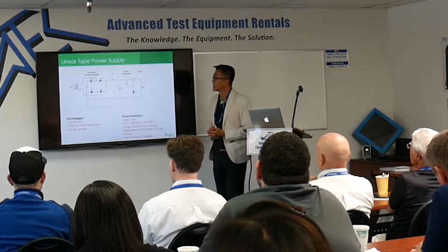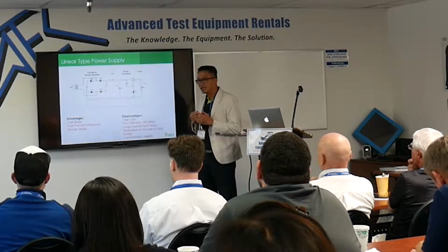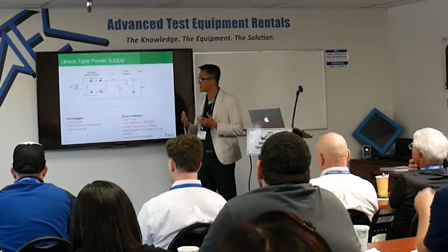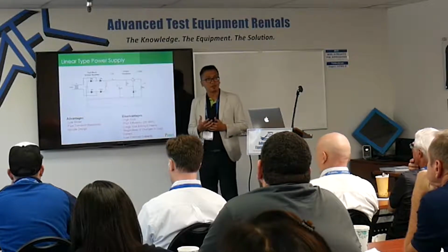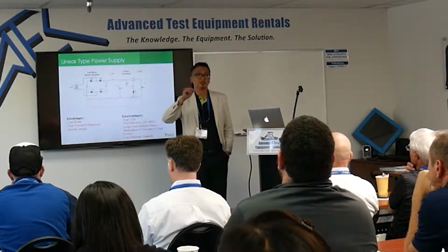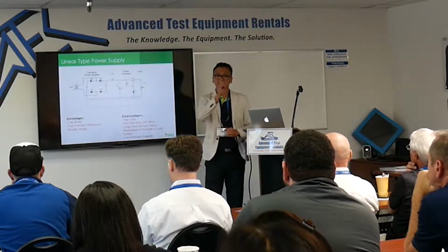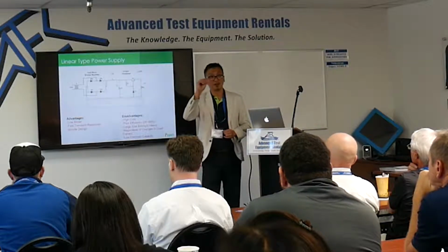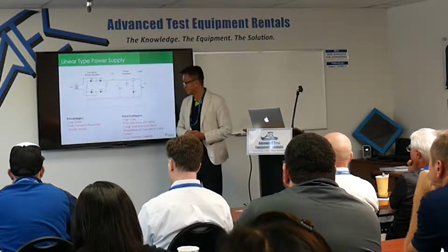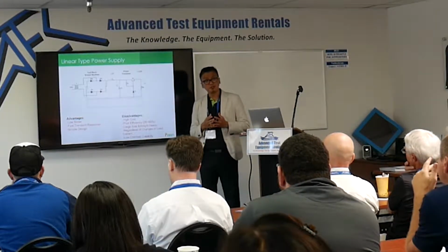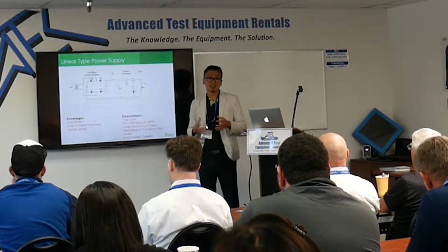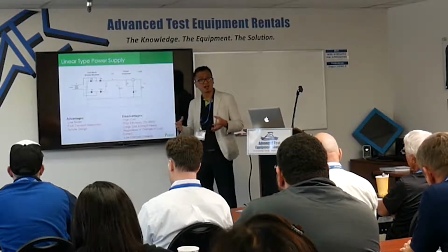And here shows up some linear advantage. Linear type of applications, the advantage of that, everyone knows that it should be low noise, because there is no switching noise on the linear type power supply. So you will not see the little spike there. And everyone thinking a fast response time and design is simple. But the disadvantage will be because it's linear, it's usually very heavy. And the size will be bigger, and the cost will be higher.